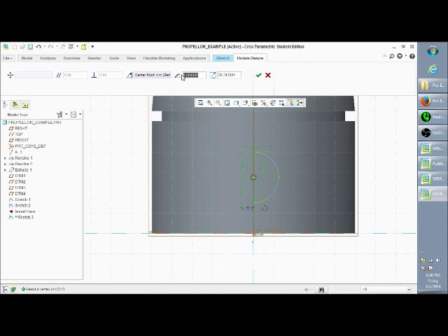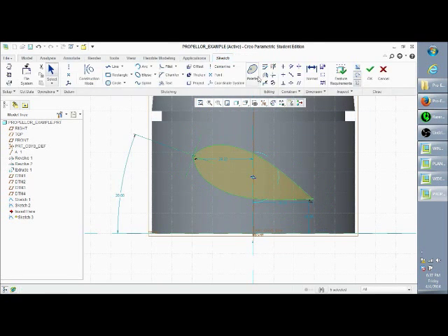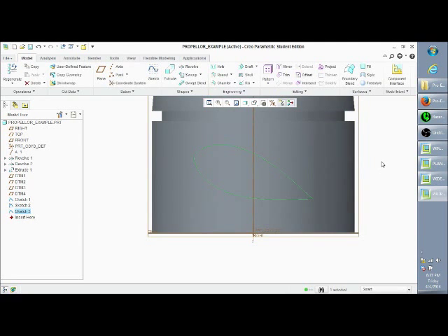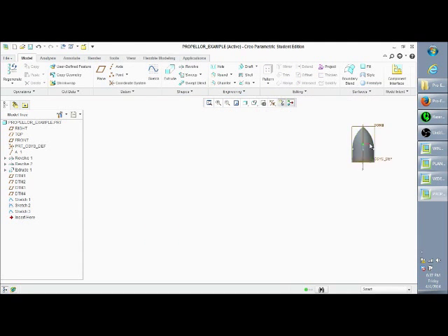So for the rotation angle, we want to set this one to 70. And then for the scale, we want this one to be 65. And hit enter, and there it'll scale it to the shape we want. And everything looks good to me, so I'm going to go ahead and click OK. And everything looks good here again, so I'm just going to go ahead and click OK again. Let's zoom out and then show you guys what it looks like now.